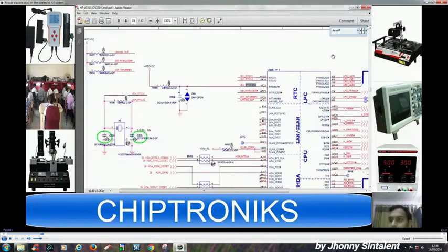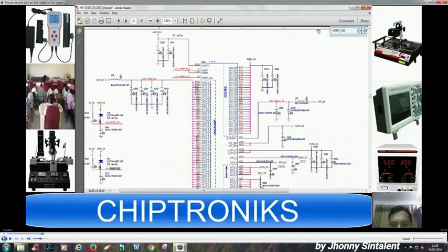So we just go and see where this signal is coming from, V5 REF sus. You can see V5 REF sus, all those signals mentioned in the data sheet would refer to the name inside the chipset. You can see the V5 REF underscore sus name is inside the chipset, whereas outside the chipset the name has changed. It is ICH underscore V5 REF sus.